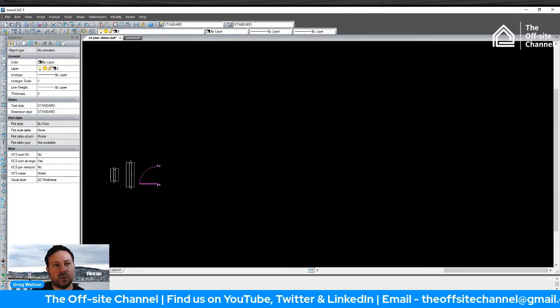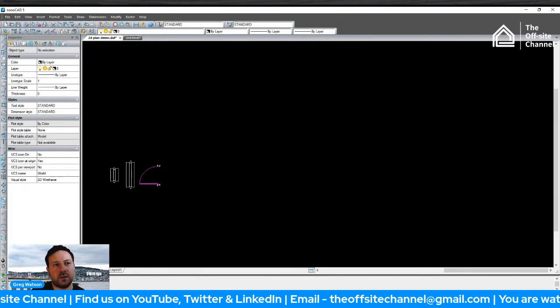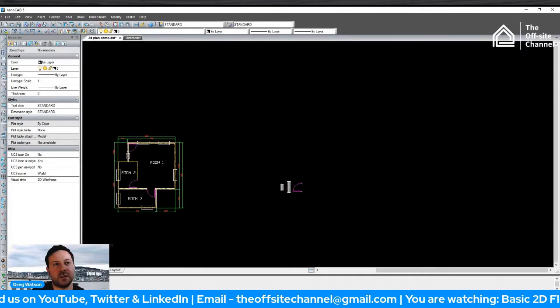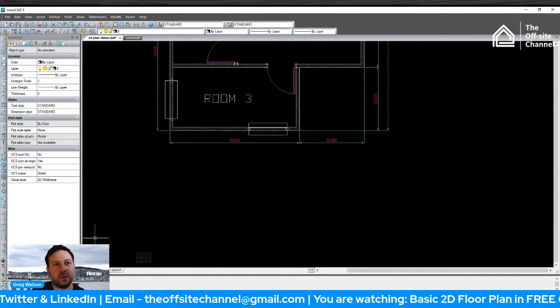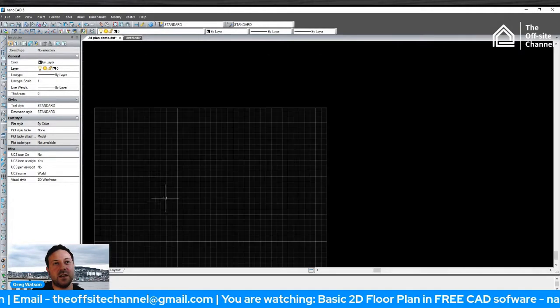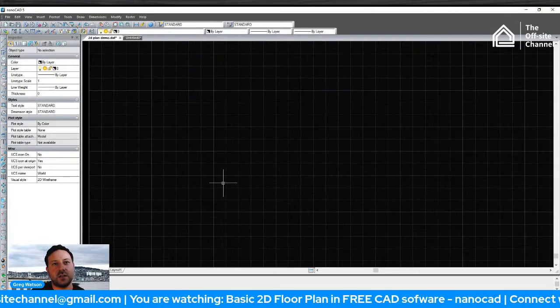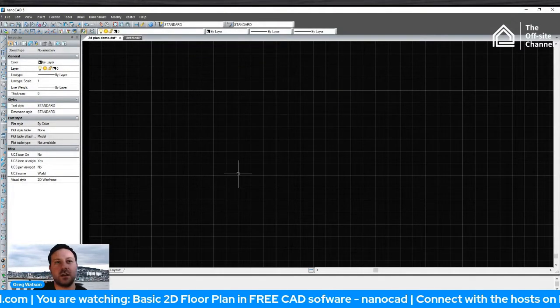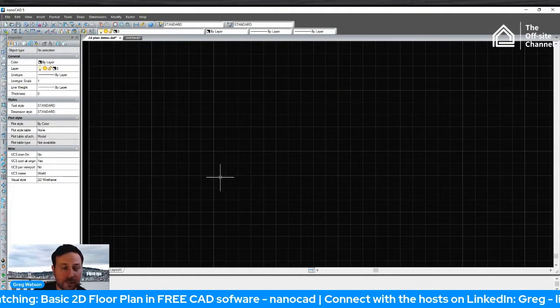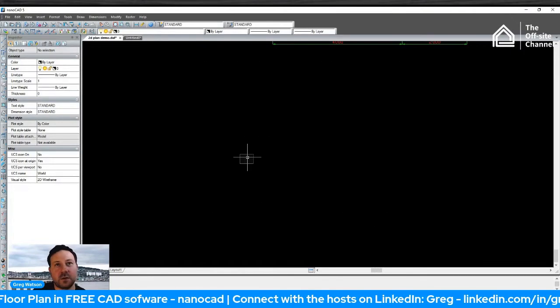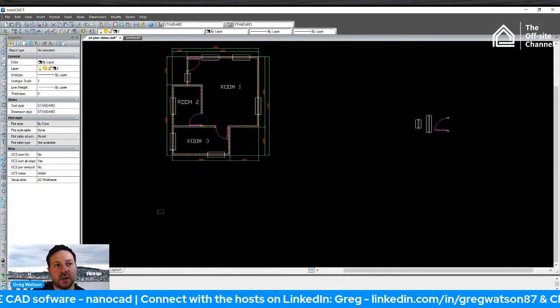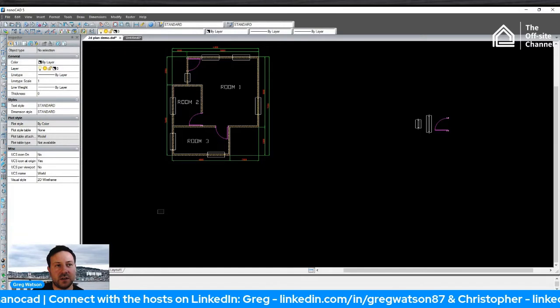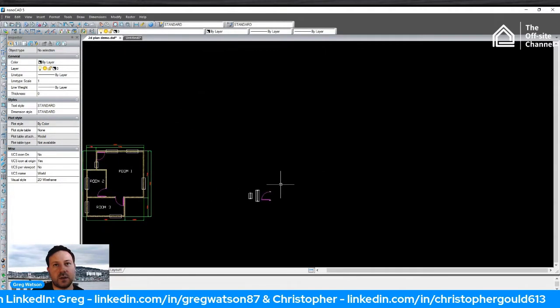So you put the grid on. Oh, here it is here. I've just got the extent set. I had it at, I think, 600 centers, or two feet for our folks in the United States, and you can change the grid limits, etc., and the steps. That's what they call it. So you can alter that there.